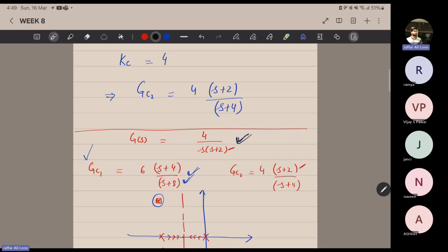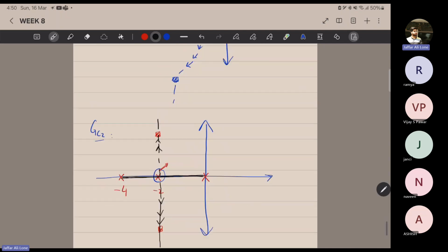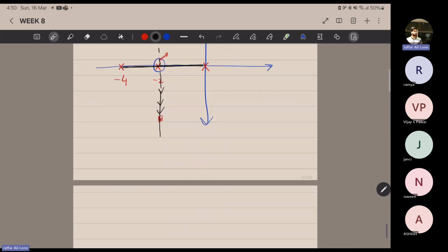You have an open loop transfer function, you have compensator 1 and compensator 2. Just join them in feedback, then see the step response, right? Then again with this desired pole, the overshoot should be 16% and settling time should be something. You can see that GC2, the lead compensator for which there is pole zero cancellation, is more accurate. The calculations for that are more accurate. So that's what I said. These are design problems. They have n solutions, right? So this was for learning purpose.